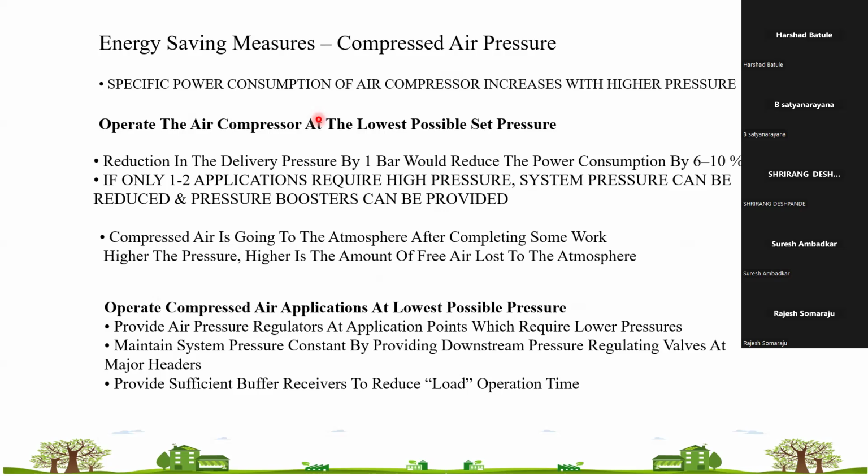If you see the same compressor in Pune, in Mumbai, and at higher altitude like the northern states, the same compressor gives different performance parameters. Like a 15 kilowatt 100 cfm compressor at Mumbai will perform differently due to ambient conditions. It is near sea level, but it is a humid condition, so your performance will be different.